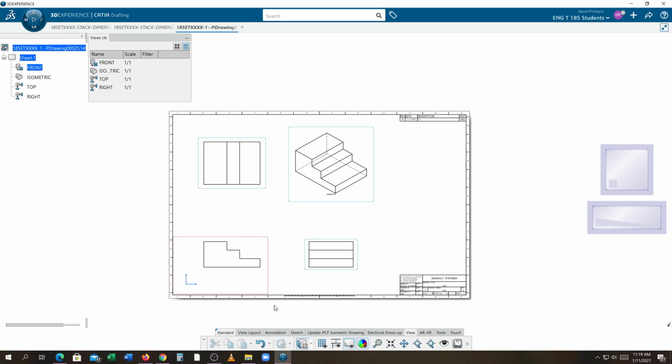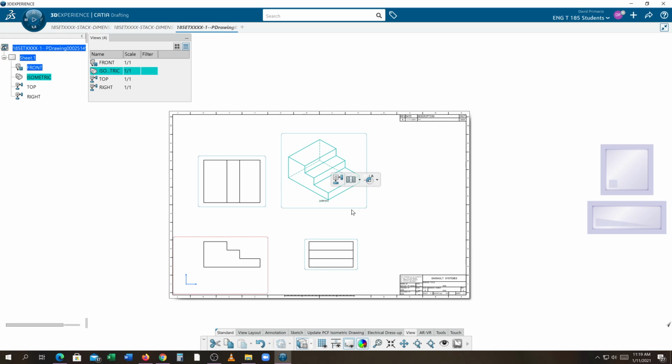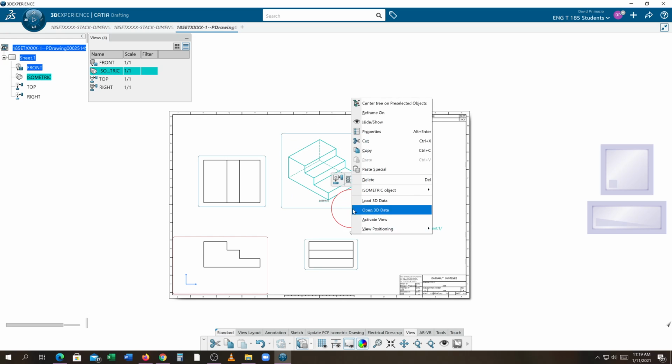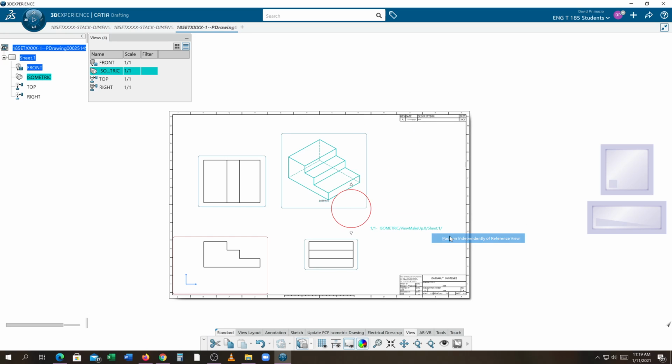Now that I have them in the border here, I might want to drag this a little closer. I might not. I might just leave it, put all my dimensions in, okay, and then mess with it later if I want to adjust that. If you have it way up there, it gives you lots of space to go ahead and put on your dimensions. Let's change our position to independent so I can move this independently.